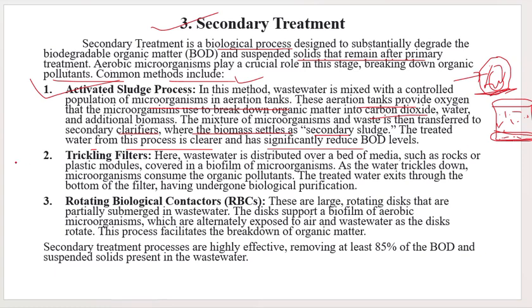Okay. Then another method is the trickling filter. Here the wastewater is distributed over a bed of media. For example, I will make a diagram. There will be one bed of media. Bed of media means there will be lots of materials such as stones, sand, that kind of media placed here. So here the wastewater will be distributed. A bed of rocks or plastic modules covered in a biofilm of microorganisms.